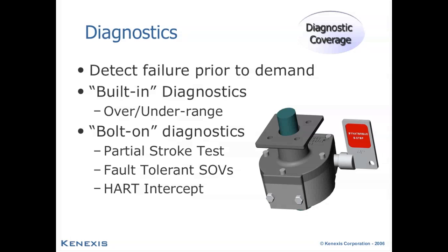Diagnostic testing can be either built in to a device, such as the overrange or underrange detection on a transmitter, or it could be bolt-on diagnostics, or diagnostics that we've configured as part of the system implementation, such as partial stroke testing or fault-tolerant solenoid-operated valve testing that allows us to, with some defined frequency, test the system automatically while online without providing any disruption to normal process operations.